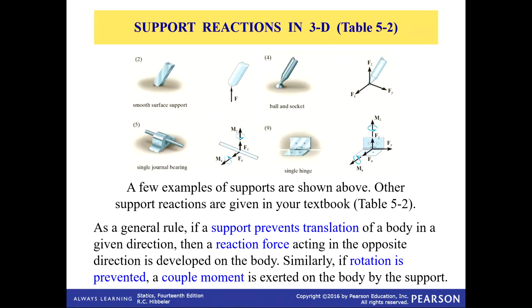And we talked about a hinge already before, right? A hinge has a moment around one axis, the axis where the pin is. Every other direction you should not be able to spin it or move it as shown there. So you've got all those reaction forces associated with a hinge or pin.